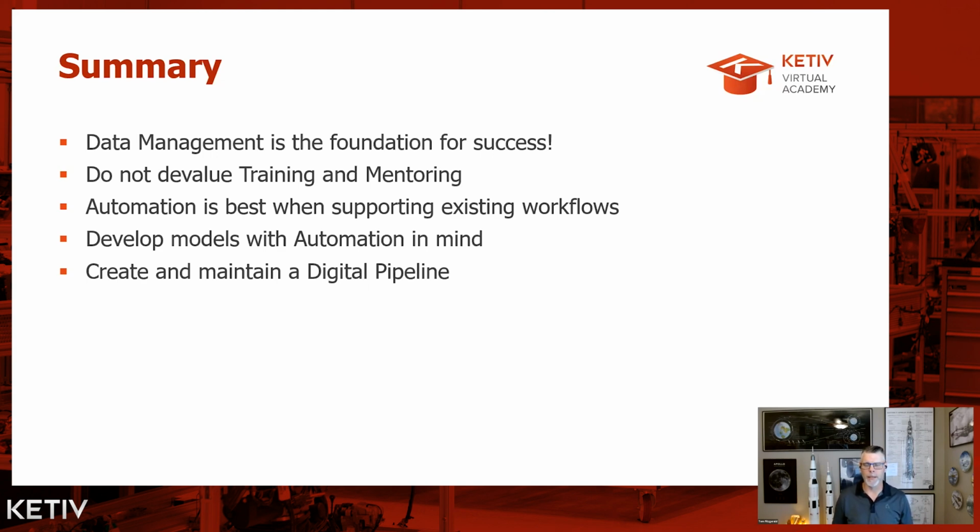Parameterization, naming convention for properties, parameters, documenting. This is a big thing, right? If you're going to create automation, and particularly if you want to do it on your own, if you're going to create automation, come up with a naming scheme. What does this name mean? This is the format I want. What kind of value goes into it? Is it of a text value? Is it a numerical value?